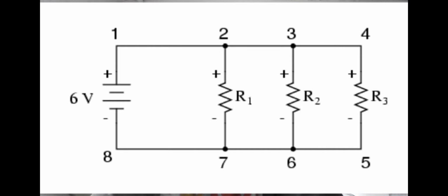So now, we should logically conclude that the total sum of all the voltages in this circuit is also 0 from this careful analysis. So since we have justified Kirchhoff's voltage law is true for both series and parallel circuits, it should logically follow that it is valid for series parallel circuits as well. Although of course, like with normal series parallel circuit analysis, you have to be careful about applying different rules for parallel and series circuits when appropriate, and not simply assuming the voltages will add up neatly, as if it were a series circuit alone.